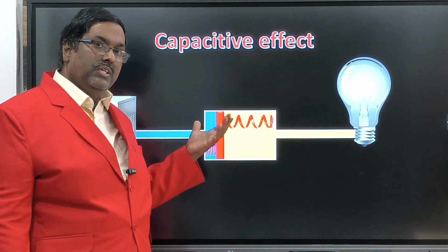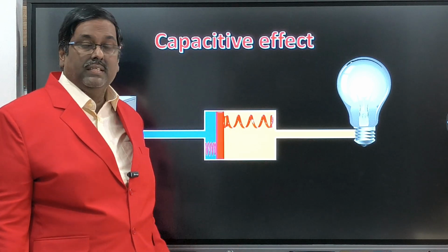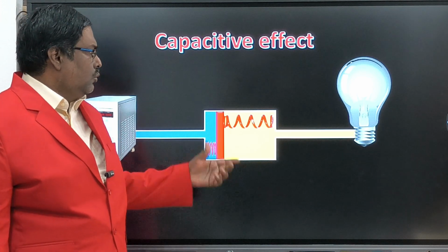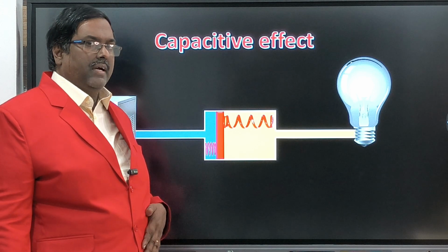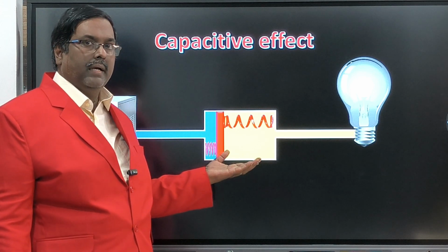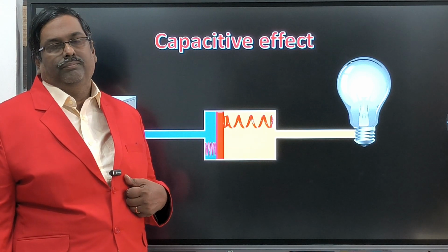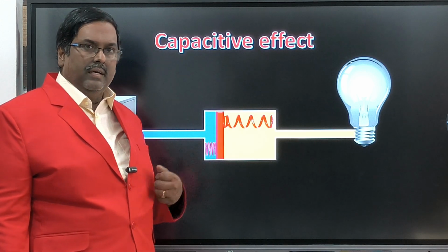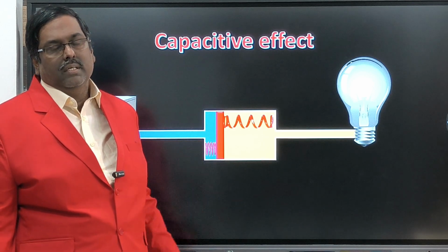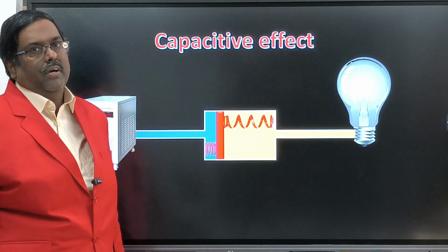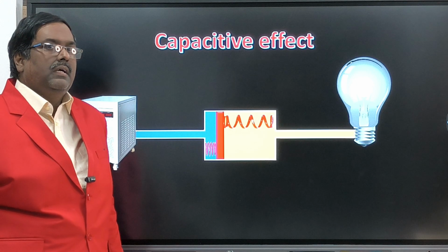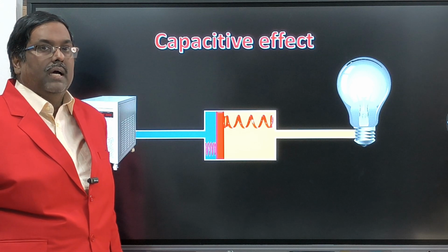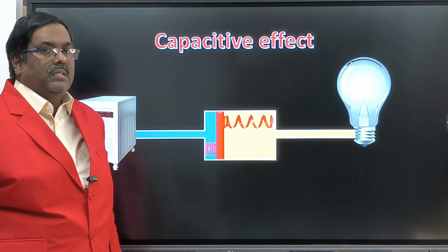So wherever the inductive load is too much, we have to use the capacitive bank for improving, what they call a power factor improver. There are two ways we can improve the power factor, which we will discuss in the power factor class. One is by capacitor bank, another one is synchronous motor. We will also discuss the future shaft generator, how it is working. In that we are using a synchronous motor for improving the power factor, because the shaft generator has very low RPM while developing the power supply. So for that, a power factor improver is a must.